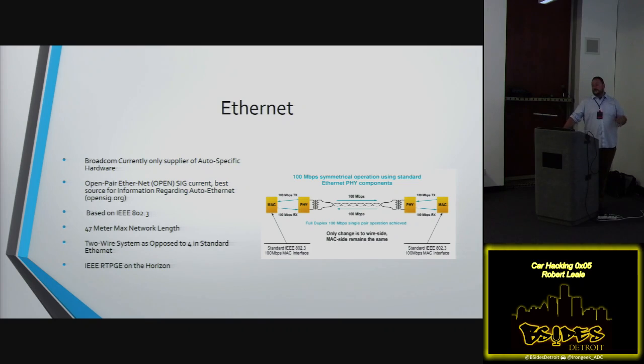It is based off of standard Ethernet, 802.3. So if you get an adapter for standard Ethernet to open Ethernet, you can actually send and receive data on Ethernet. What that data will be, it's not necessarily going to be TCP/IP packets. It might just be proprietary data that they ship. It might be their own proprietary protocol, which is very common of OEMs.